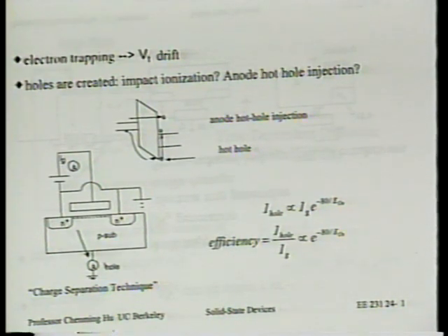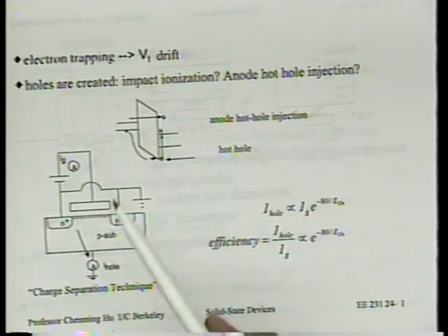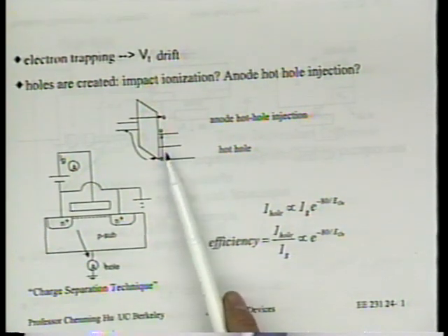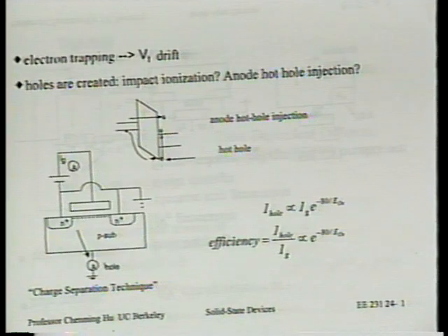In other words, this efficiency, the ratio of the hole current to the tunneling electron current, that's the Fowler-Nordheim current, let's say, that ratio also increases with increasing voltage. See what I'm saying? All right. In other words, for every, say, 1,000 electrons tunneling through this oxide, one hole gets created, right, at some electric field.